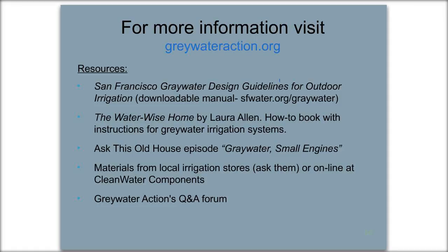But about every year you should be checking on a simple system. You don't have to replace all the mulch, but you probably are going to replace the mulch under the graywater outlet. So you'd put your gloves on, get a trowel or a small shovel, and remove the decomposed mulch, which is now great soil, and then replace it with fresh wood chips. So it's not a very labor-intensive process, and it should be done about once a year.